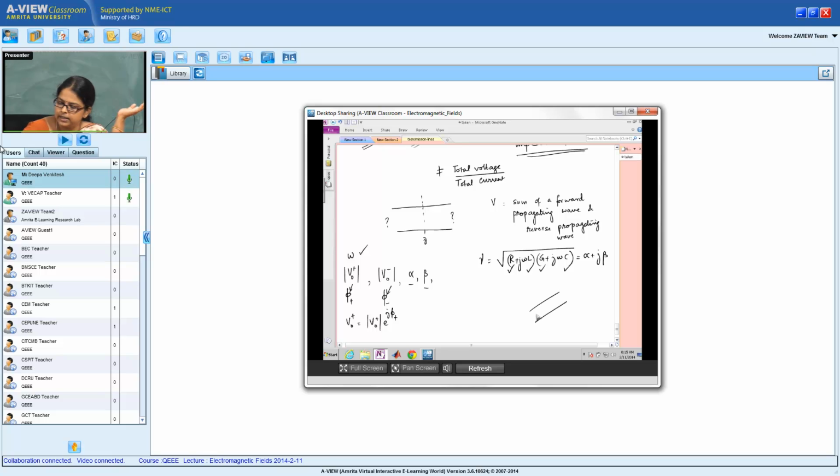If I take a coaxial cable, the center line is the hot line, and then you have the ground. I look at the cross section, it is like this. You have a dielectric here, alright. I can measure the resistance, inductance, conductance, capacitance. All those numbers are measurable quantities, which means I know what alpha and beta are once I have picked my line. Omega, as I said earlier, is a frequency that you are applying, so that is also known to you. So if R, L, G, C are known, alpha and beta are known, omega is known.